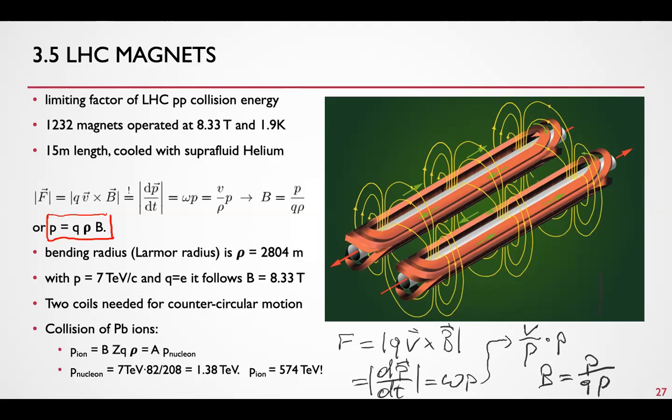It's not difficult to achieve 100 Tesla. It's possible, people do it. They shoot the current into a magnet that explodes, and you get 100 Tesla. It's not what we are doing here. We want to operate the accelerator continuously, so it cannot explode. It cannot quench. It needs to have structural integrity. We barely achieved the 8.3 Tesla, so that's really technologically challenging.